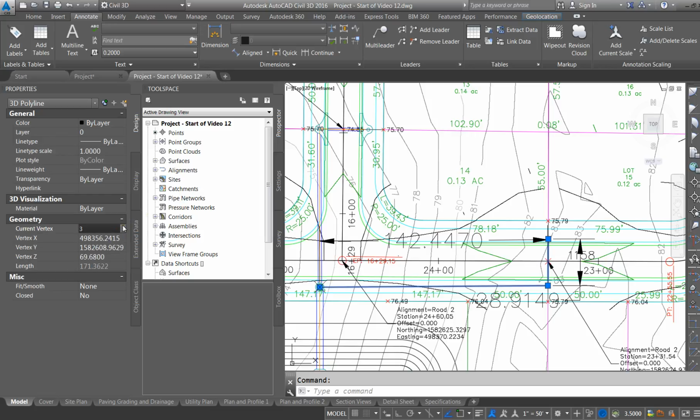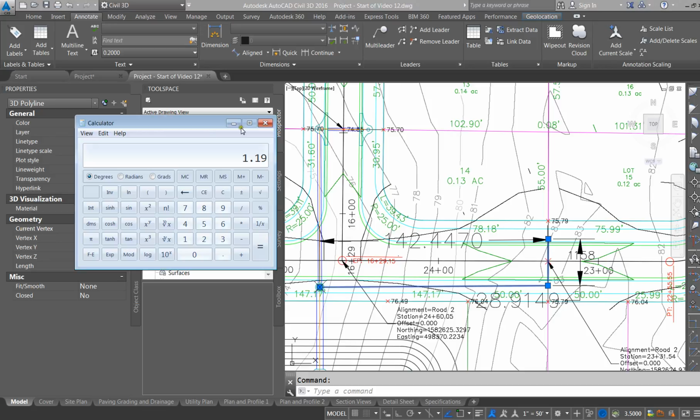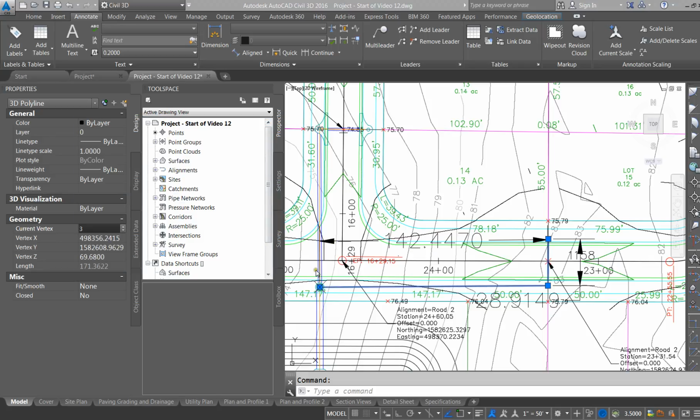My third invert is going, if we use the 69.93, clear that out, 69.93 minus 0.0025, because that's our slope, times 142, that's going to give us 69.5. So the invert that we had this one set at, so that elevation is going to be, well, we've tied it into 69, so it needs to be 69.5.